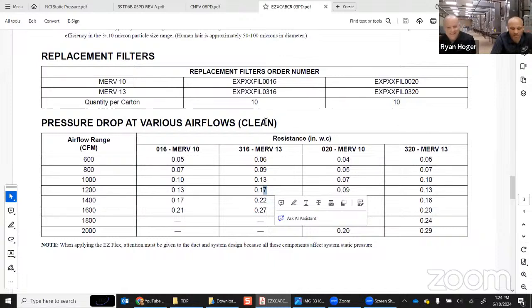The same thing will happen with coils, right? If we have a coil that's a certain capacity of cooling and we're doing it in a little short stout cabinet versus one that's tall and has more surface area associated with it, you're typically going to have a higher static pressure drop through that as well. So sometimes with the coils, even though we've used N coils for a long time, they're nice because they fit in small spots, but sometimes fitting in a small spot means everything's jammed in there, which means it's a little more resistive.